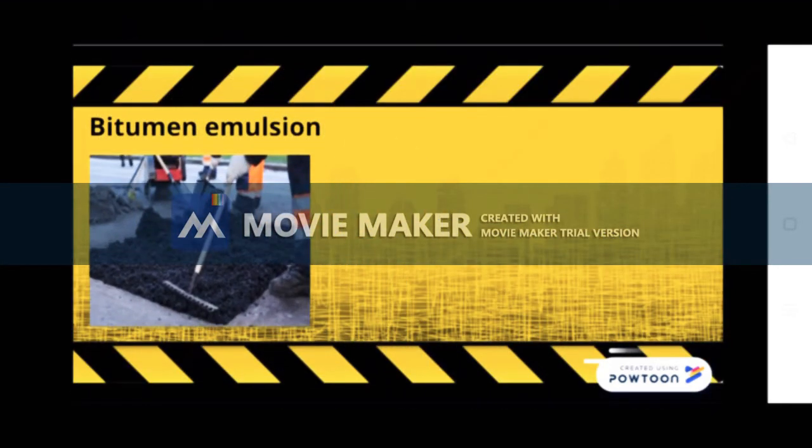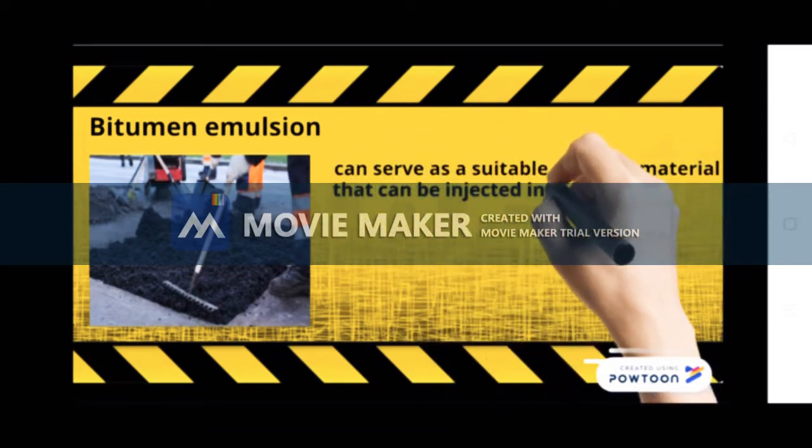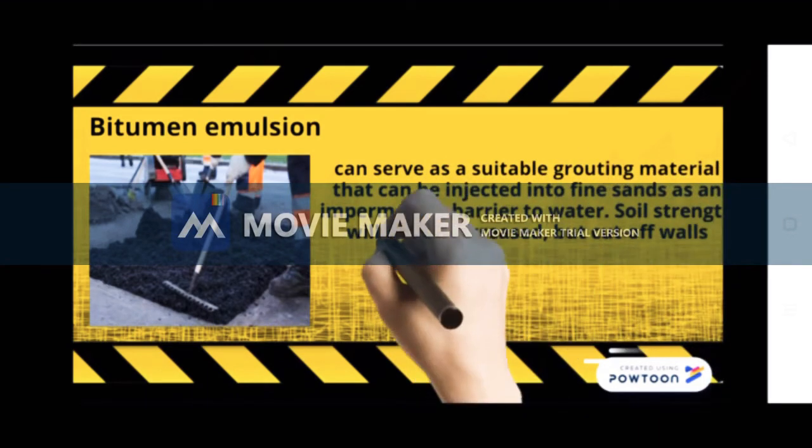Bitumen emulsion can serve as a suitable grouting material that can be injected into fine sands as an impermeable barrier to water. Soil strength will not be increased, but cut-off walls beneath dams and other water-bound structures can be formed effectively.